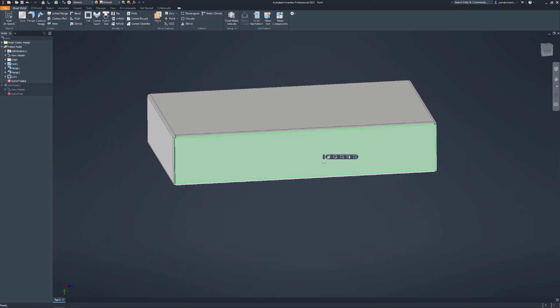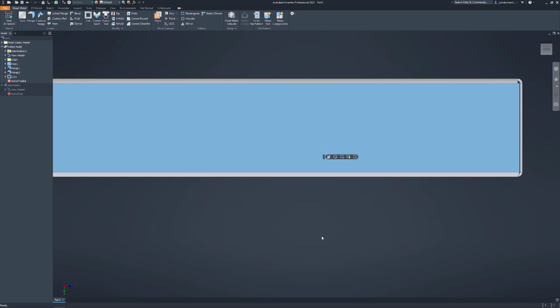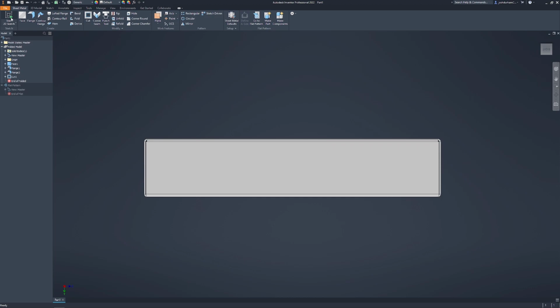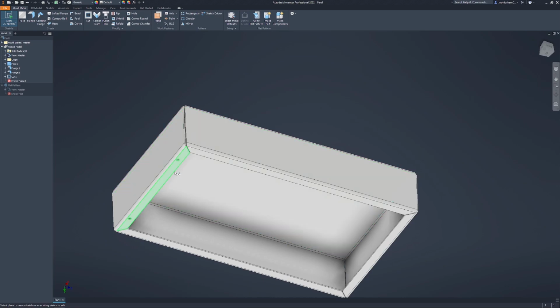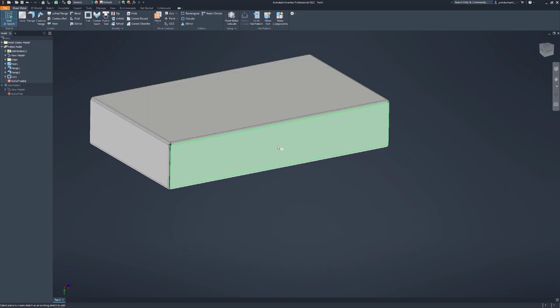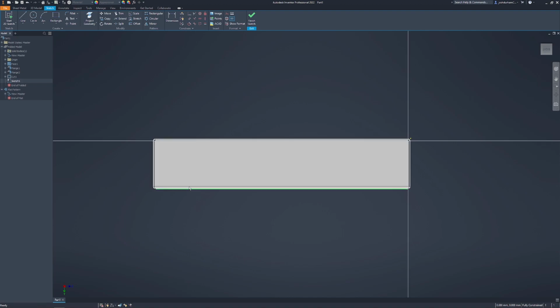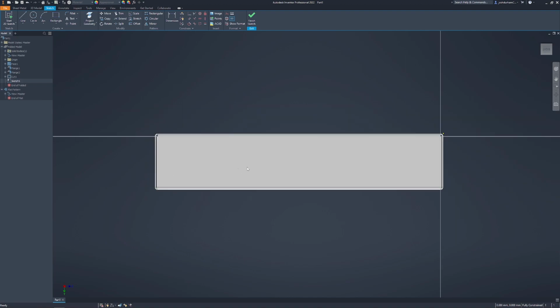That's fine. We want to add something to add in all your control knobs, etc. It's one of the benefits of having these parts laser cut instead of buying in enclosures and drilling them, that you can get precise cuts and repeatability every single time. So we'll start a 2D sketch, and this time instead of selecting the face under here, we're going to select the face here. So this flange is where we want to apply this sketch to. And we can see that it's already oriented it there, so we're totally flat and square on.